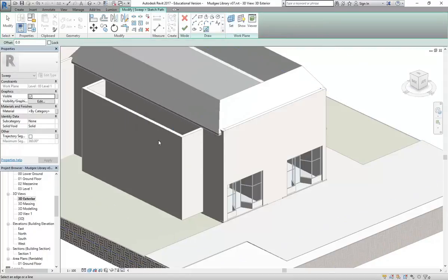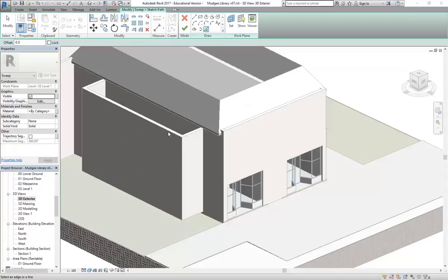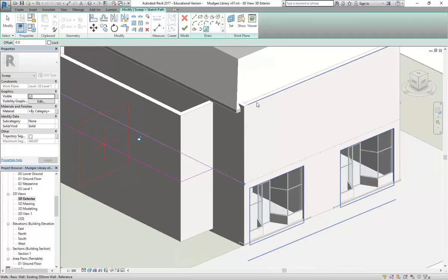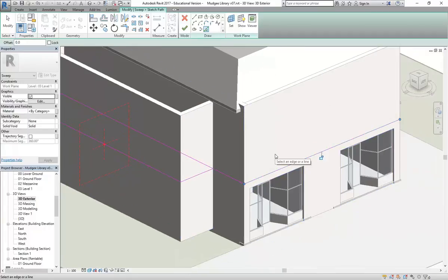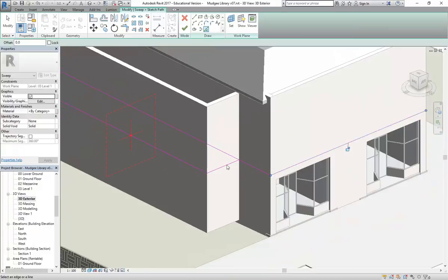And then with pick lines, I'm simply going to pick the outside of these walls, and I might just check if it goes. Yeah, it goes around that building too. So I'll just choose again the face of this wall, and then the face of all the other walls that I want it joined to. And notice how it's projecting onto the plane that I've picked. That's why it knows to put these lines automatically at that height.